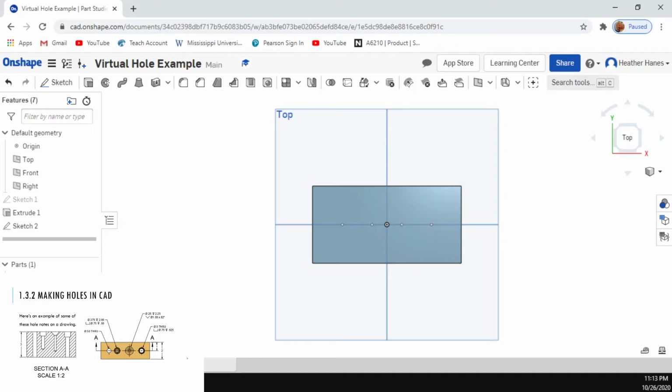Now anytime you've got one sketch and you have multiple features you're going to use multiple times, you're going to use the hole tool on it, you're going to use multiple extrudes. The first one you do, it will make your sketch in your feature list here actually turn invisible like that. So there'll be one feature but you won't be able to see the rest of it. When that happens, make sure you hit show your sketch again. It'll show all those pieces you didn't use yet.